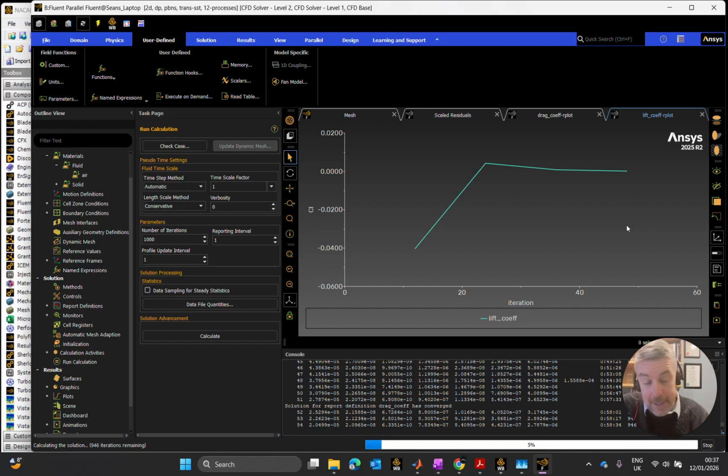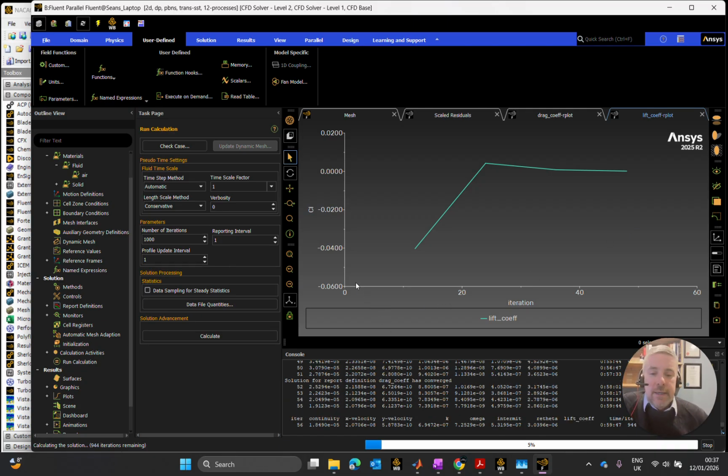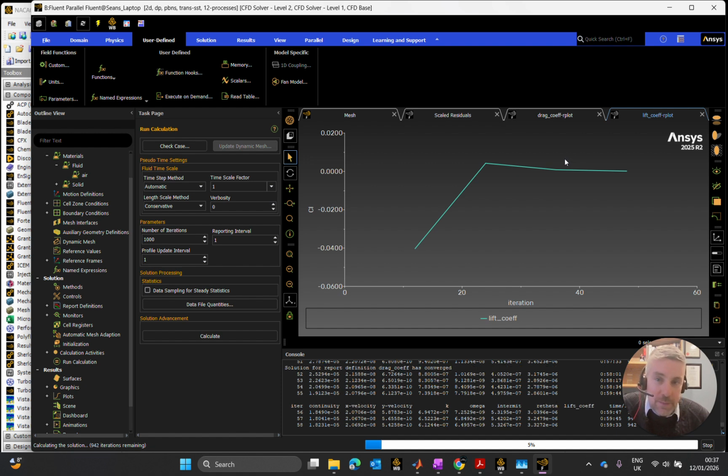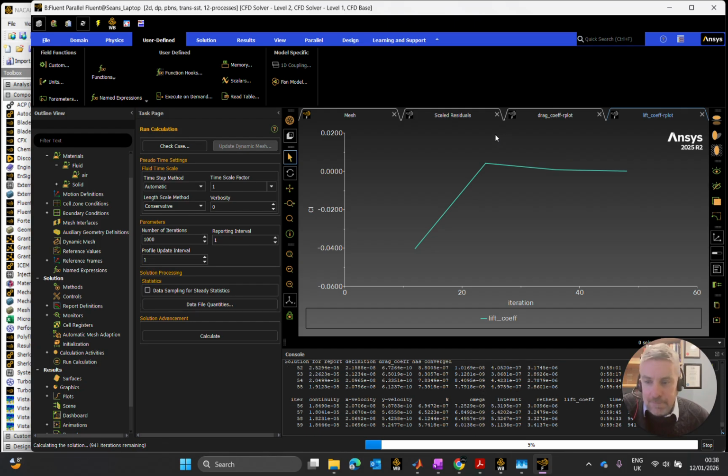Yeah, NACA 0012 will do it, but you might have another option to look at, which will not be as sensitive to developing laminar separation bubbles, especially ones that might not necessarily reattach.